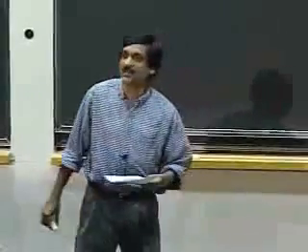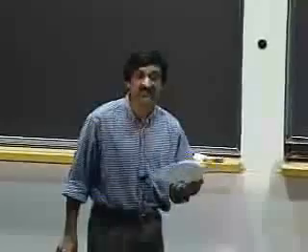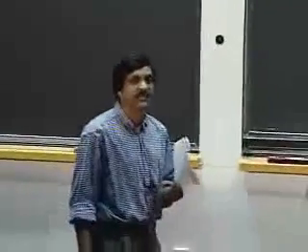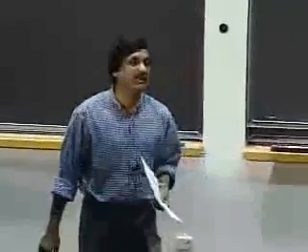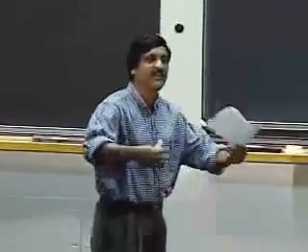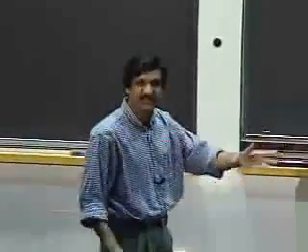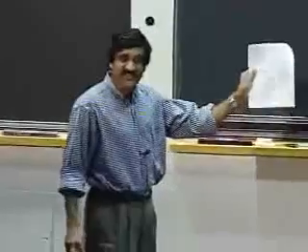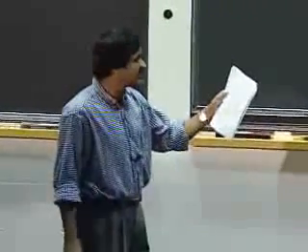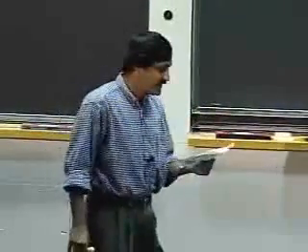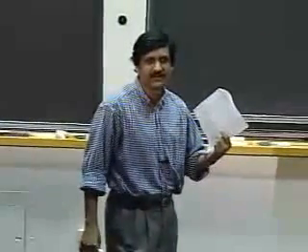So I've circled 2 things on page 2. One thing that I've circled is power supply range in the 0.7 to 1.3 volts. Notice that the power supply voltage for these chips is significantly lower than the 5 volts that we've been nominally talking about in this course. When in doubt, our problems have used 5 volts. But notice that in this technology, they're talking about using voltages for the power supply, VS, in the range of 0.7 to 1.3. So why is it so much lower?